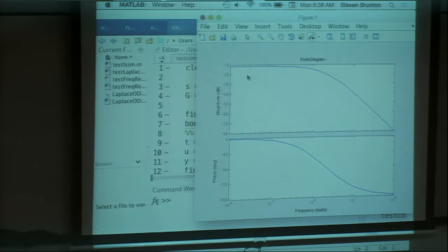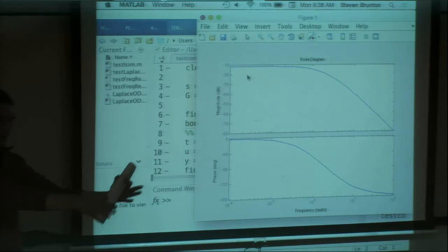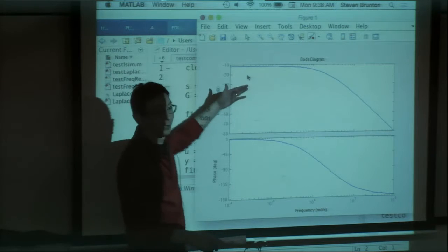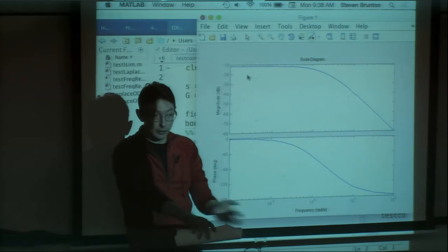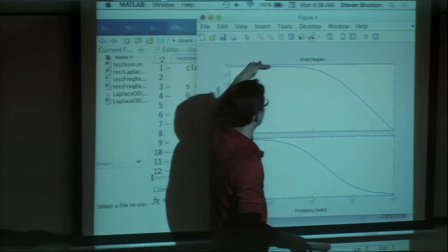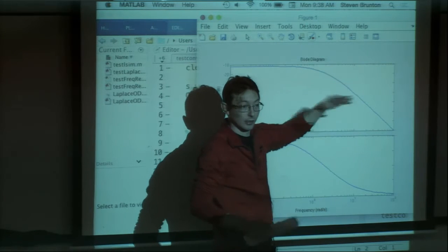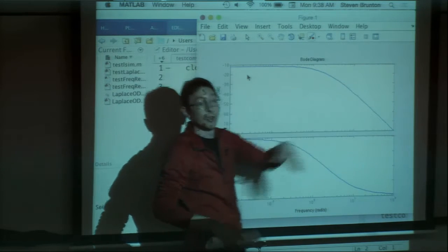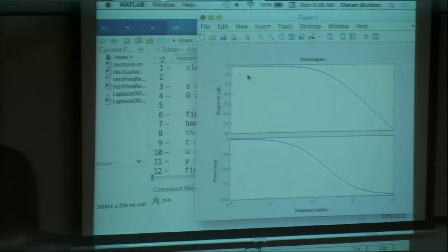It could cause failure. So on an airplane wing, I would want to do the frequency response of the actual wing to different aerodynamic frequencies, low frequency turbulence, high frequency turbulence. And I want to make sure that it doesn't have any big resonant peaks that's going to cause the wing to be shaking or vibrating, because that'll essentially cause fatigue and eventually failure. Okay, so you do this on essentially all testing of materials where you think that you want to have a long life and there's going to be some vibrations involved.